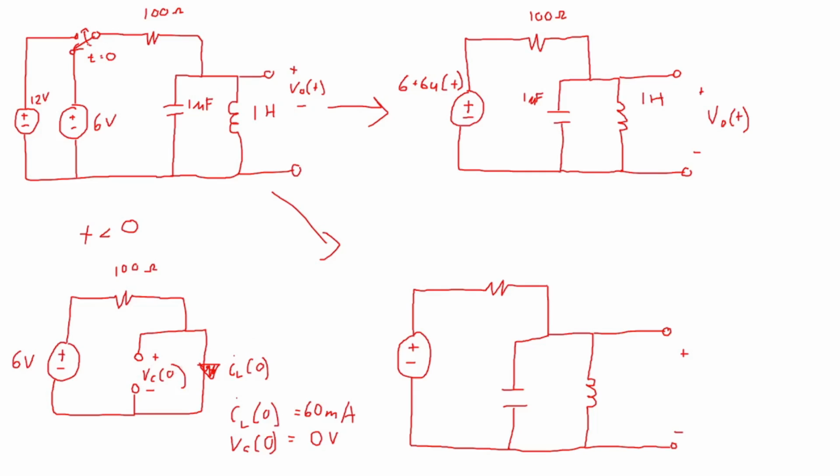Okay, so in the original position, after a long time, this resistor allows a current of 60 mA, all of which flows through the inductor after the capacitor has completely discharged, because of the inductor discharging that capacitor down to 0 by acting like a short. So these are our initial conditions. So I might kind of run these clicking now.